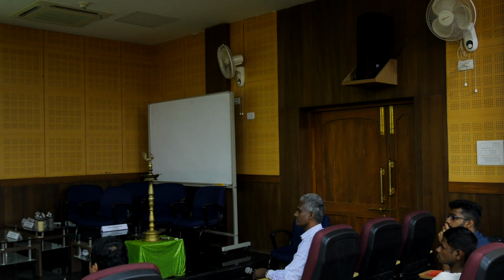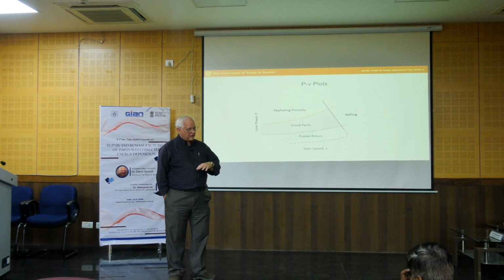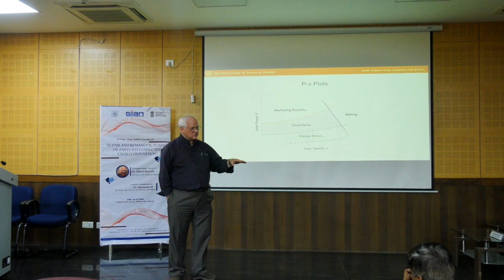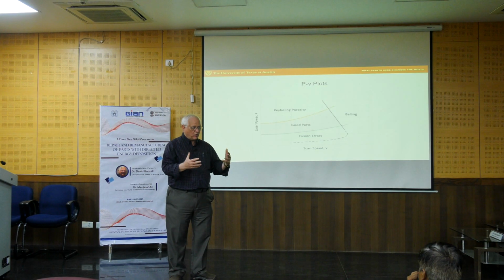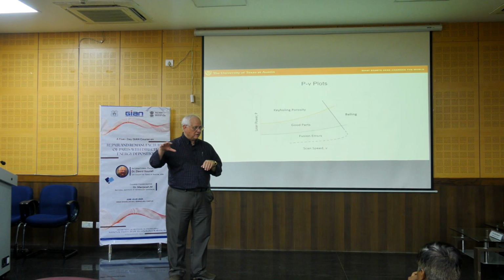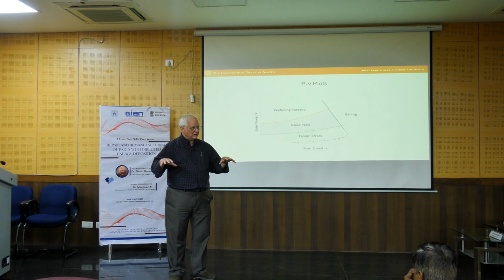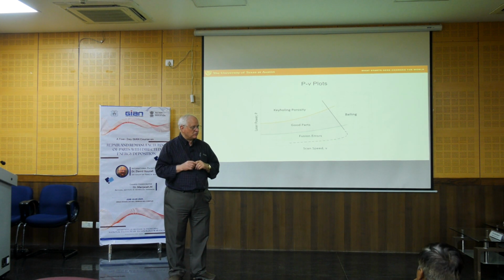First of all, on the distinction between powder bed fusion and directed energy deposition, and again this is very broad and very general, directed energy deposition can build with faster build rates, whereas powder bed fusion is perhaps best characterized by the finish and the accuracy of the geometry.